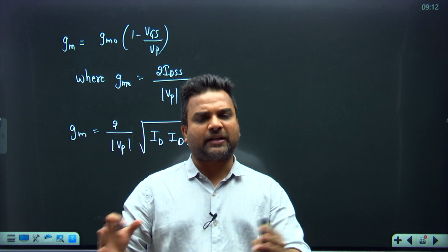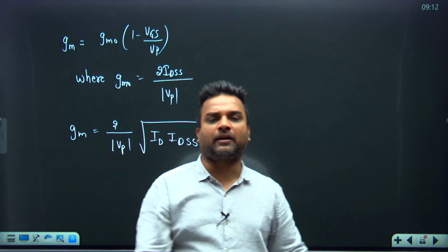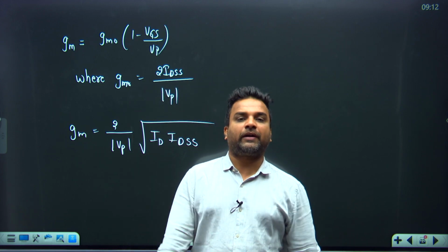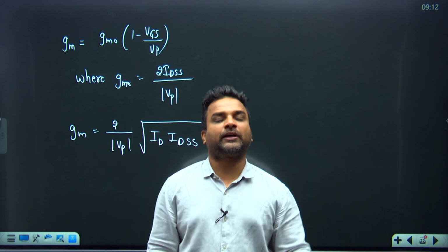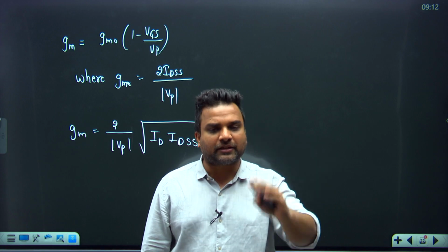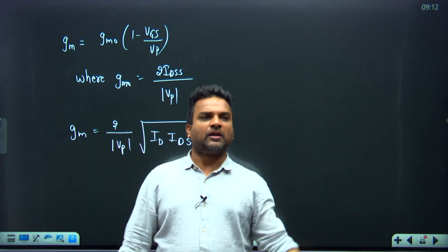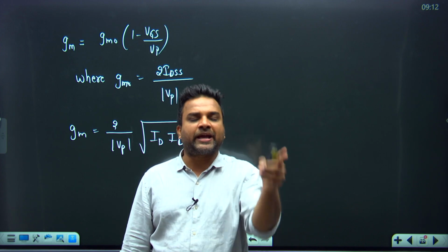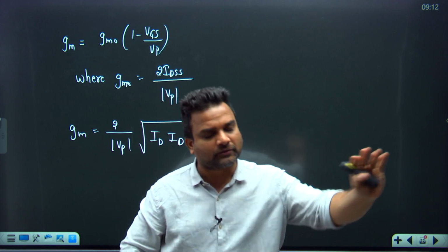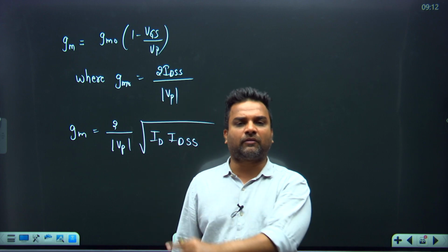Why does JFET not have any thermal runaway? Why only BJT has thermal runaway? Because BJT is an NTC device. Whenever temperature increases, the reverse saturation current increases, IC not, so that IC increases, so that there is more heat which destroys the transistor after some iterations, some cycles. That is what thermal runaway. Being an NTC device, thermal runaway will happen. Any device, if it is an NTC device, thermal runaway will happen.